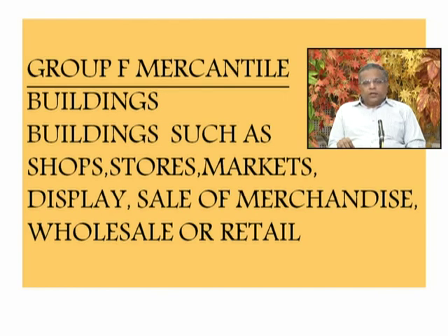This mercantile building is for display, sale of merchandise, wholesale or retail. Where this type of market transaction is made, normally it is a shop or a showroom. These buildings come under the category of Group F, that is a mercantile building.